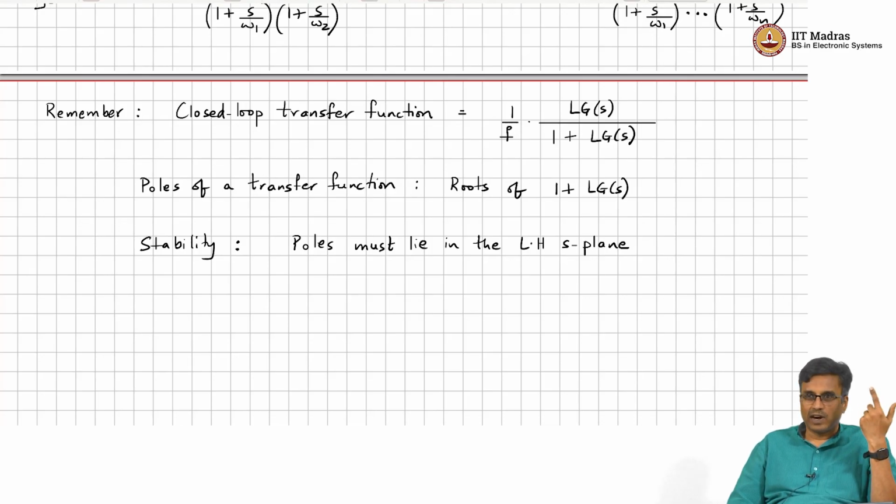Yeah, the other person gets very annoyed. That is why, whenever you make a telephone call, the standards say that the latency cannot be greater than a few milliseconds, because otherwise it just makes the other person angry or annoyed. So whenever there is a lot of delay in a feedback system, it can cause the system to become unstable. Stability is something you always have to worry about whenever you take a system with memory and put it in a feedback.